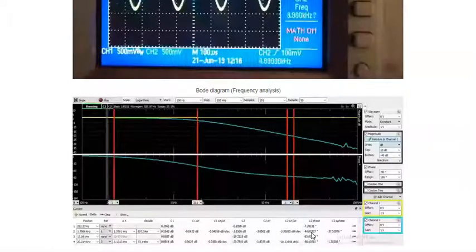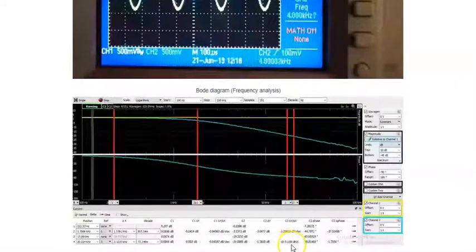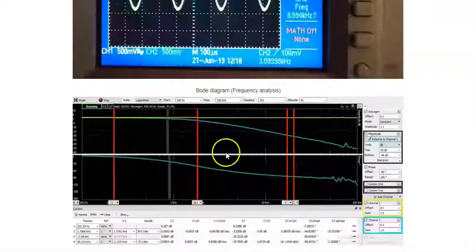The ratio of magnitude to frequency of cursor 3 and its delta is found to be -18.9115 dB per decade, whereas ideal value is -20 dB per decade. This corresponds to roll-off of the filter circuit.